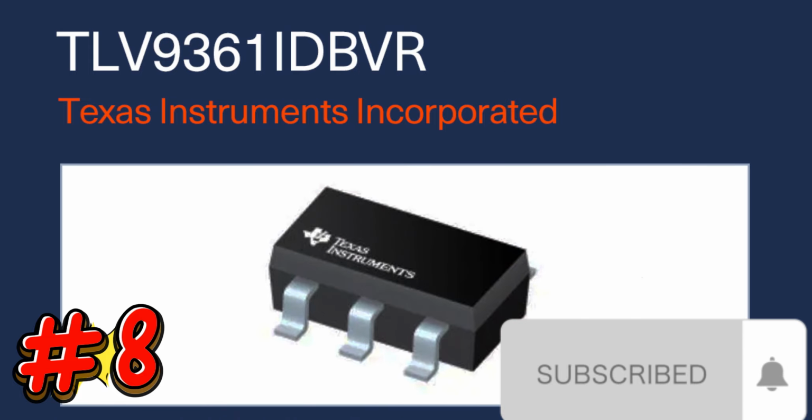It has a low input voltage noise density, low offset, and low offset drift at a 10.6 MHz bandwidth. This single op amp is AEC-Q100 automotive qualified and cost optimized.